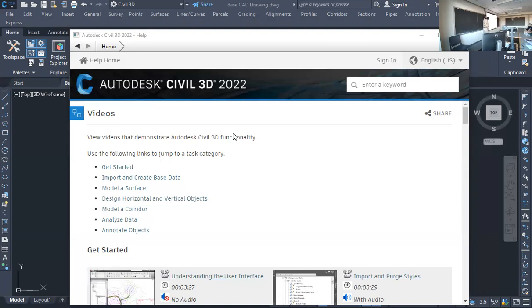Notice that it is looking for a number in that very first column of data. Because I think the big yellow data collector lets you put in anything there. Like you could put in benchmark, or like you could put in text. It's looking for a number. So you'll have to change that if yours is different. The program won't import the file.